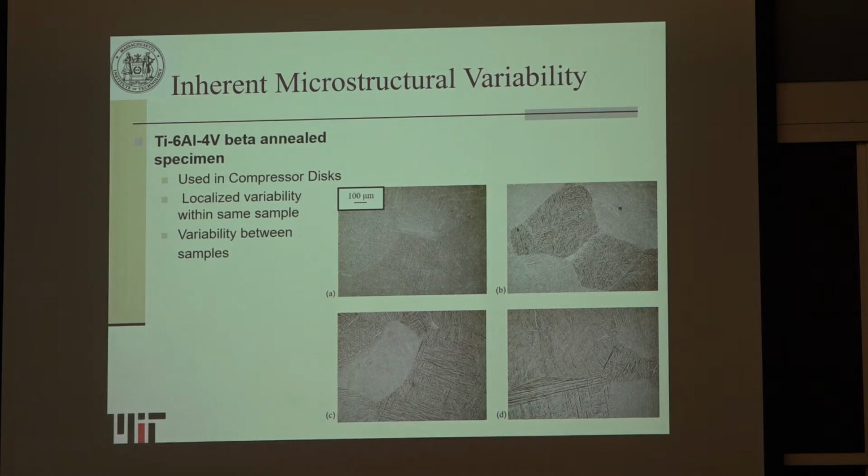So these are things that you can't really design against. You have to just take into account when you're doing mechanical properties that you have a range. It's not just a single value. And you have to understand that if you have isolated regions where there's either all beta grains or all alpha grains, that's not wanted. You want a random dispersion of the grains throughout the structure.